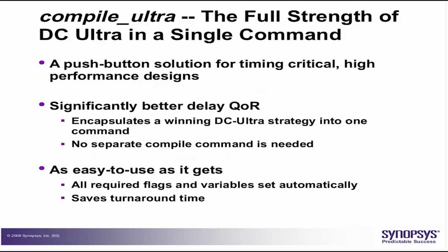So again, I'll repeat that till now in this unit 4, while we are discussing compile ultra, we've seen that in most of the cases, you as a designer don't have to do much. You just have to run compile ultra, right? If you see that your particular goal, timing goal or area goal, is not being met, then you use these advanced synthesis techniques to achieve your goals. You do some trials, but in the first pass you should always use compile ultra as a default and not try anything special. And I guess in 95% of the cases your goals will be met and you will be happy.